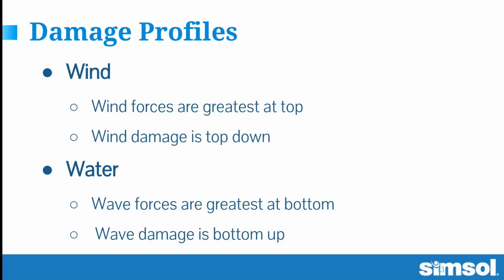Hi, Eric. I have a question for you. Sure, Danny. So, when you arrive as an adjuster and you're seeing a constant water line, we could actually have higher water levels due to storm surge, but it's not shown as a standard line or a standard point along the wall. That's correct. Okay, so something we need to look for. Yeah, typically I would estimate from my ponded water line, usually about a 2 foot wave above that in typical situations. It could be more depending on the site, but you'd have to look at the physical evidence at each site.